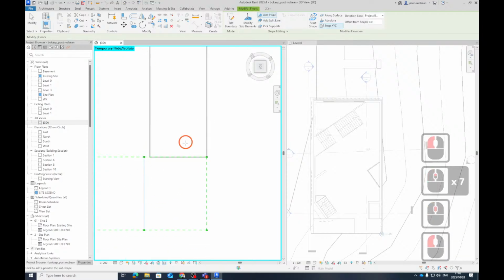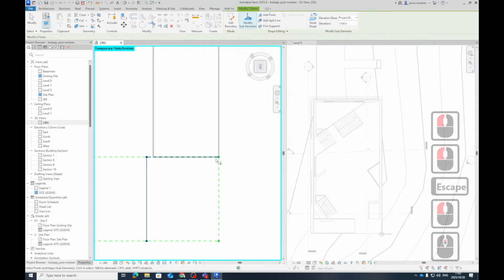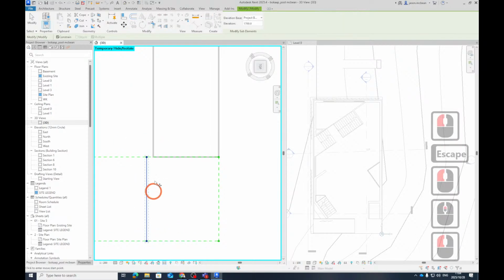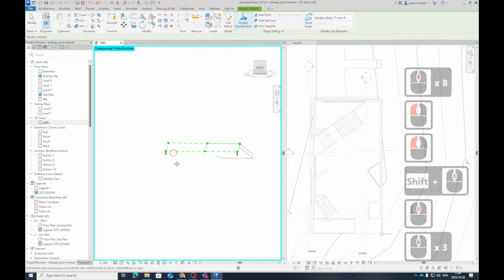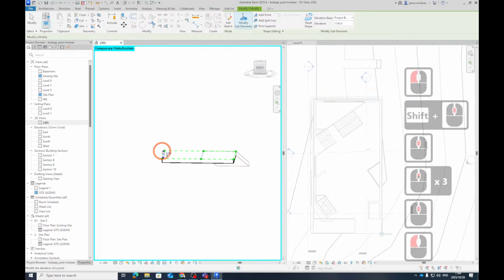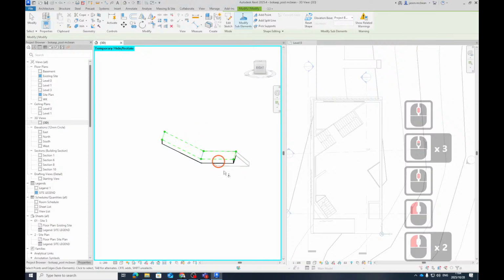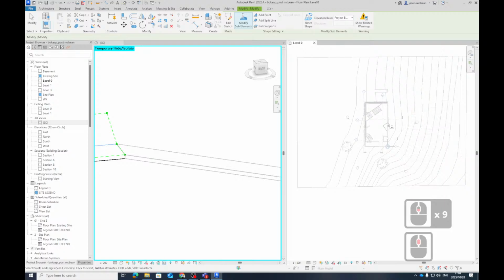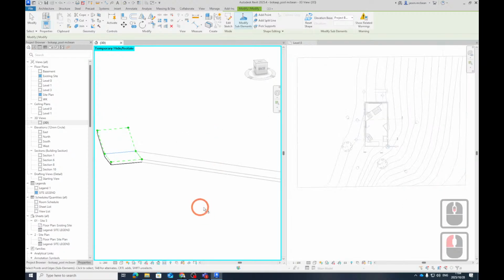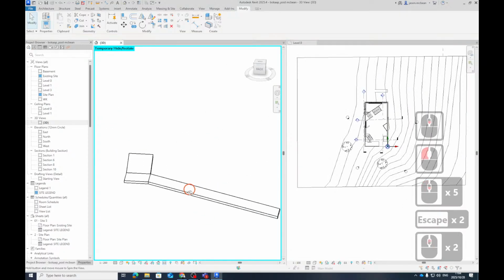And then I can go to points and I can move these points. So just escape. I can now move these points, move them so that they tie up to this point here. Bang. So what it allows me to do now, with this subsurface going on, is to grab this one and go. Now, the whole time while you're working, you might want a section open so that you can plan how the ramp must go. Okay. But there I don't use any ramp tool.